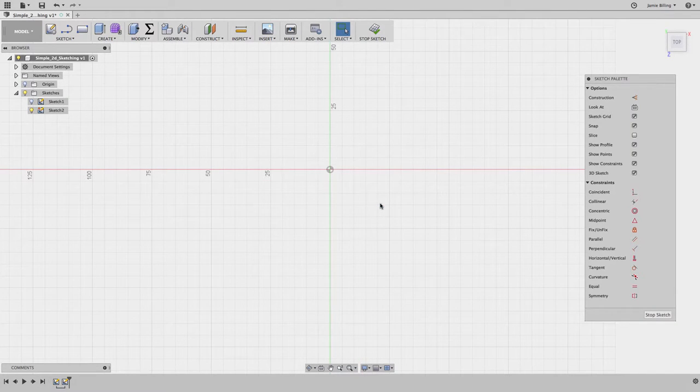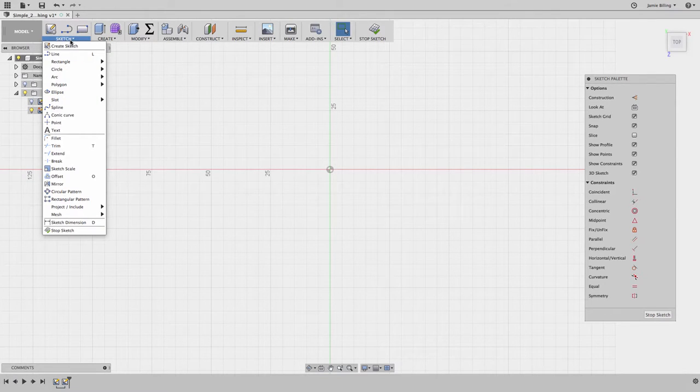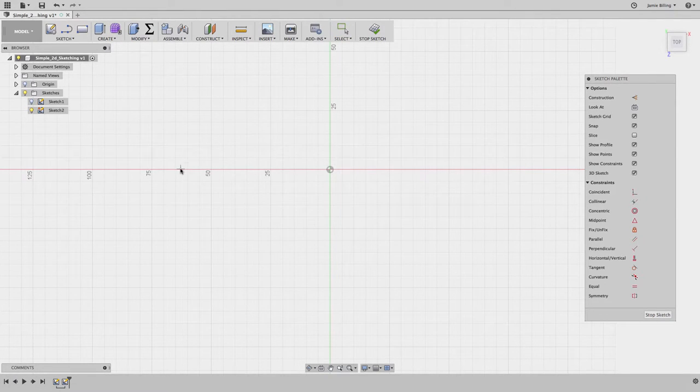To sketch a spline in Fusion, we need to go to the toolbar, select Sketch, Spline. Now let's sketch a spline with 4 points. Make sure that you place the points so that the spline has curves. And when you've finished, click the green tick to confirm the spline.